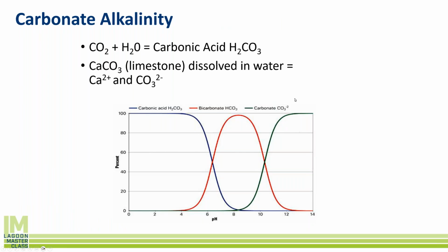Calcium carbonate is actually the unit that we measure alkalinity in. So whenever you see, say, 200 milligrams per liter of calcium carbonate, that's one way. Some people would then write down, oh, nope, that's 400 milligrams per liter of bicarbonate. So that's another way. And some states actually have a different way of monitoring it that they call milliequivalents, but we're not going to get into that.